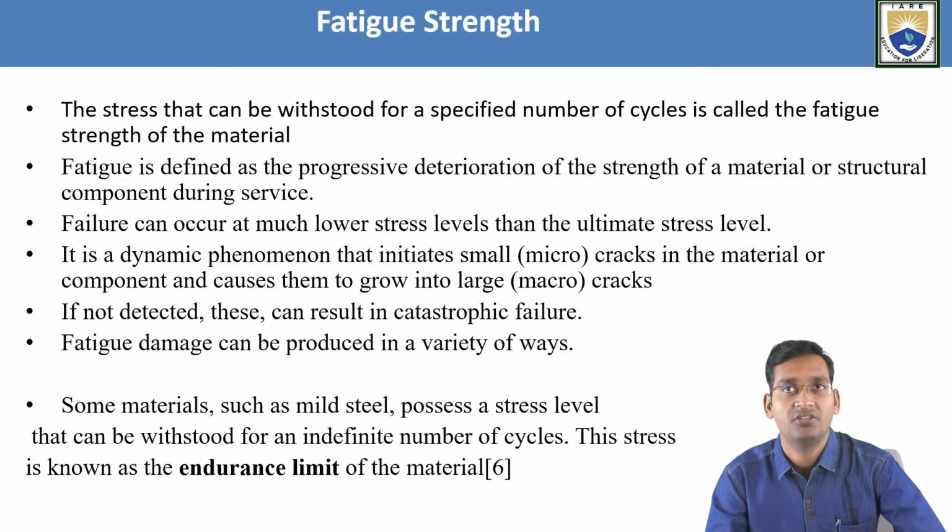It is a dynamic phenomenon, means it can progress in any direction. It's not necessary that it is in one particular direction only. It can be a small micro crack or a macro crack also. Now if it's not detected, then what happens? Catastrophic failure will occur. From that point the crack will start propagating, and finally the material gets broken into pieces depending upon how the stress is acting.